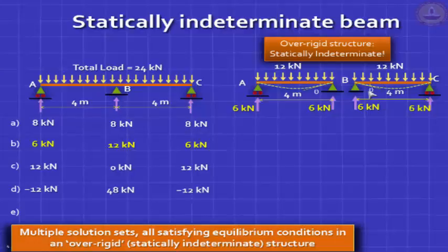You can have only one slope. It could be 0, it could be plus theta or minus theta, but both should have the same sign. So something is missing here. If you look at the actual deflected shape, you can even guess it's going to take a shape like this. The rotation here cannot be clockwise or anti-clockwise because it would violate symmetry. The left half of this picture must be the right half as a mirror image. So the only way you can satisfy symmetry is by having a 0 value of slope.